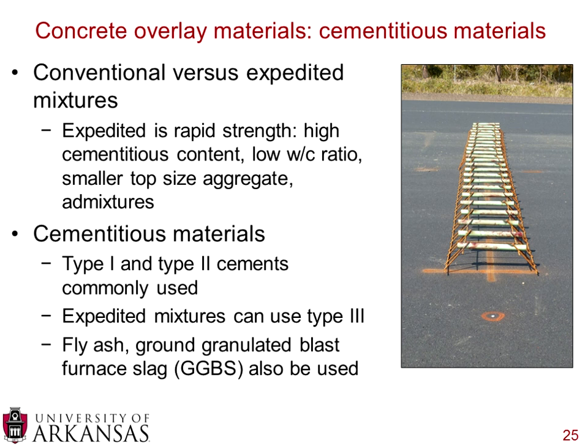And when they say expedited mixtures, a lot of pavement design considerations are driven by how quickly you can return traffic to your pavement system. Obviously, the longer a road stays closed, the higher the user delays are, the higher the user costs. So expedited mixtures try and get those cars back on the pavement surface a little more quickly.